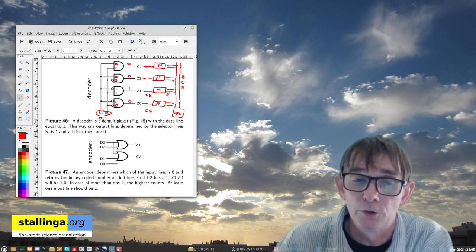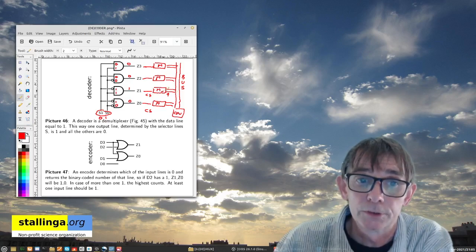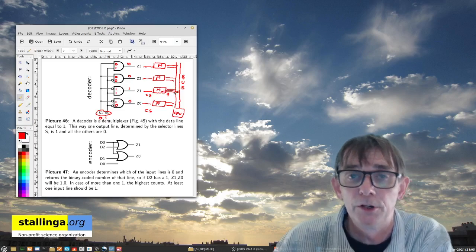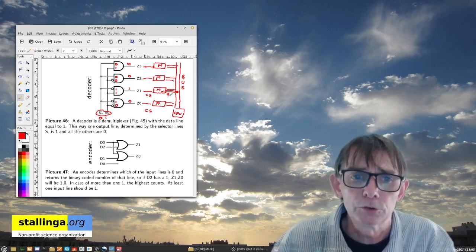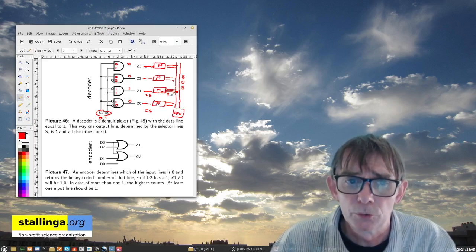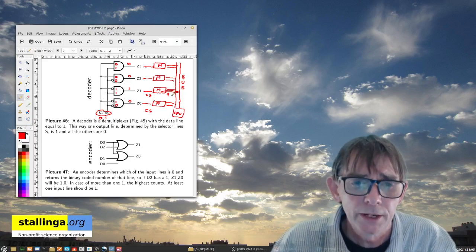But if it is taken off tri-state, then the contents of the memory are placed on the bus. And of course, we call this talking. And of course, only one of these elements can talk. The rest have to listen or be deactivated.